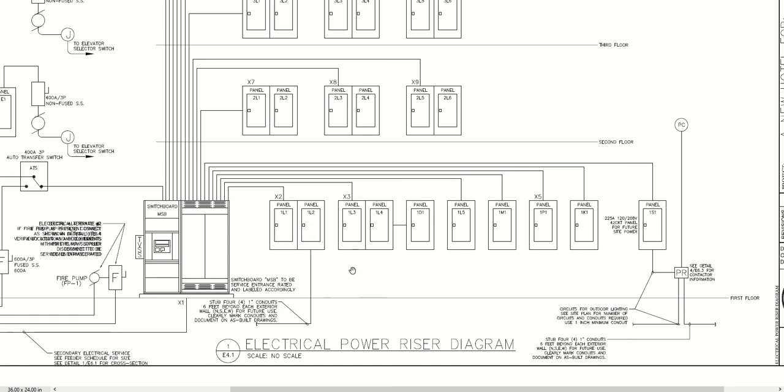It just gives us more breaker space location. Whereas in this case, you see there's a line between these two. That means there's a breaker inside of this one feeding this panel separately. This is a small lighting panel here.